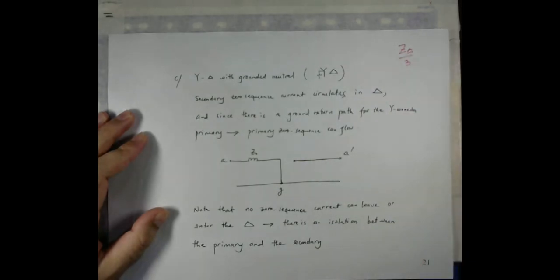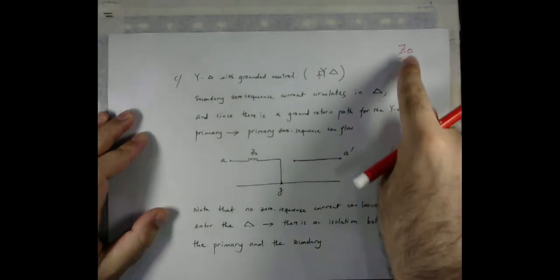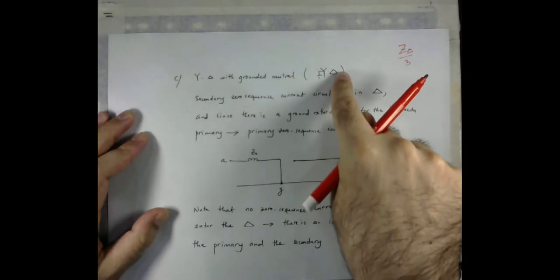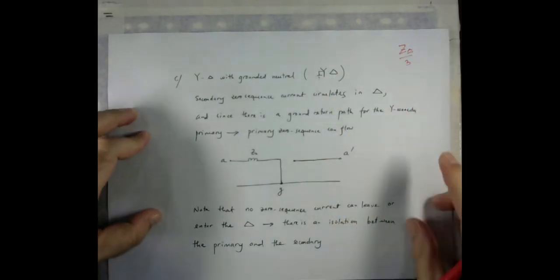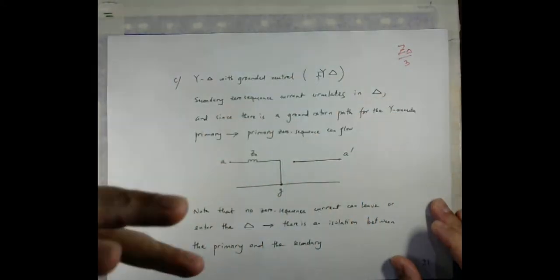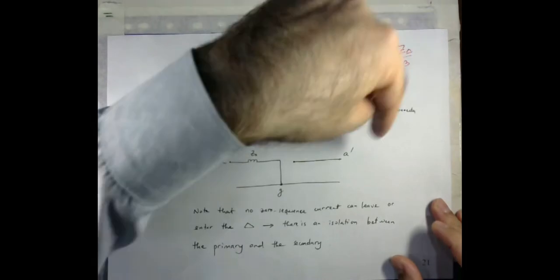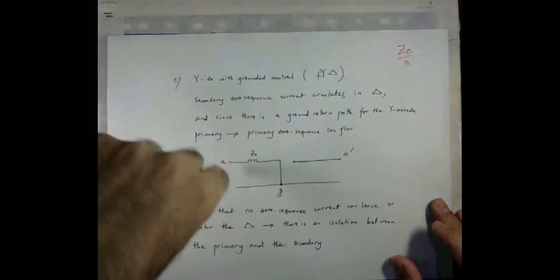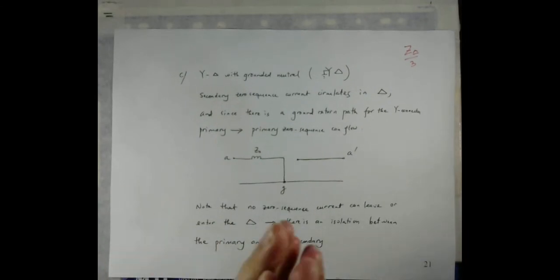And we also discussed that the currents in that equivalent Y will be the line currents which feed the delta connection, but these are not the currents flowing inside the delta connection. We discussed this before.